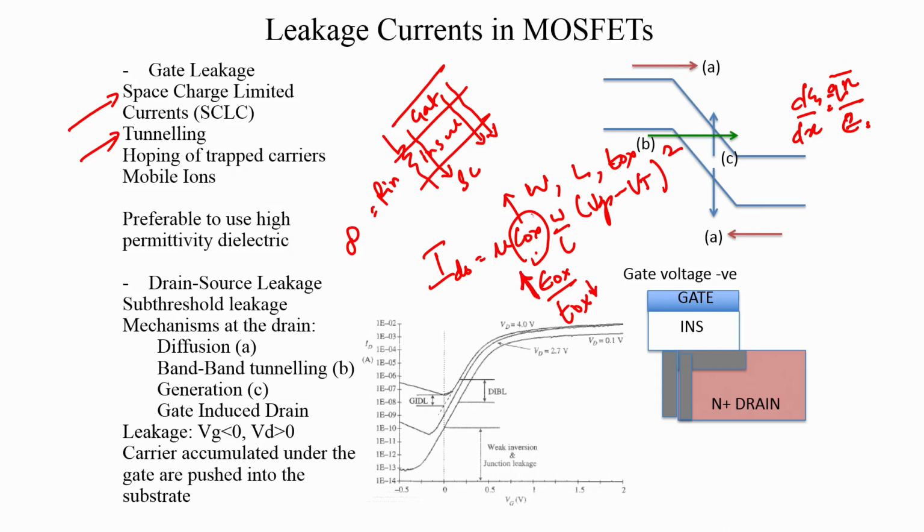And in this way we can still improve the field effect and at the same time not give in to all these gate leakage mechanisms. Now, the gate leakage mechanisms effectively reduce the input impedance. They do not keep the input impedance infinite, and they make it quite finite. Okay. And this has got implications when we design circuits.